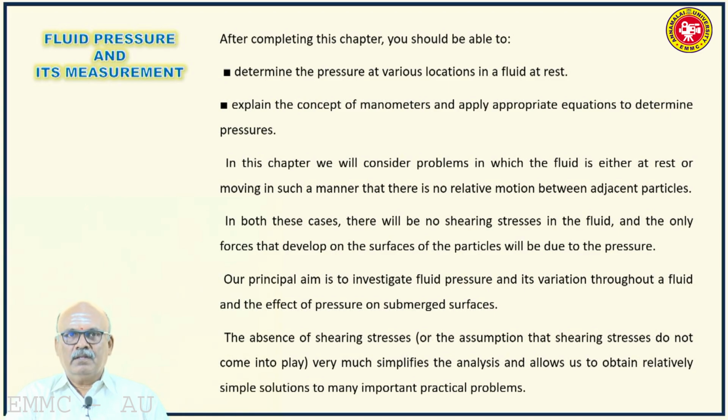So in both these cases there will be no shearing stresses in the fluid. So when you assume that the fluid moves like a rigid body, like a solid, then there is no shearing stresses in the fluid. The only forces that develop on the surfaces of the particles will be due to the pressure. So our principal objective is to investigate the fluid pressure and its variation throughout a fluid and the effect of pressure on submerged surfaces. In fact, that we will discuss in the next chapter on fluid statics.